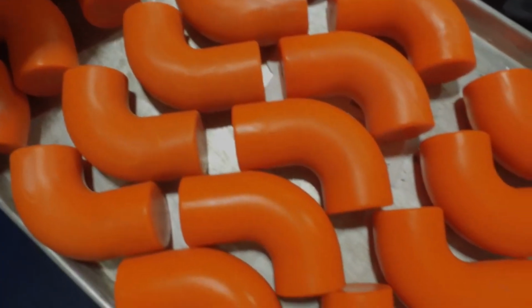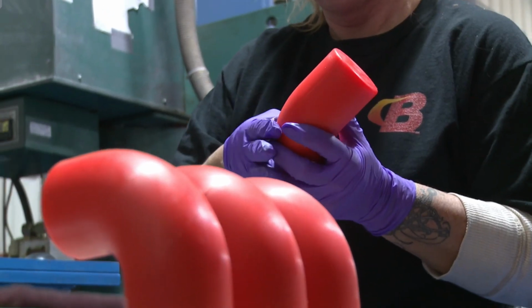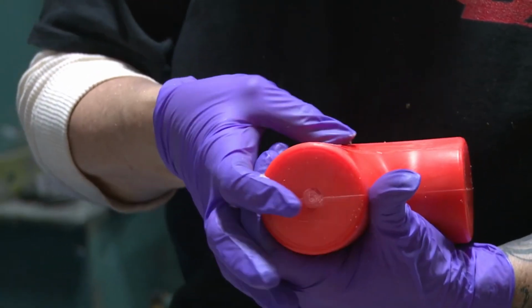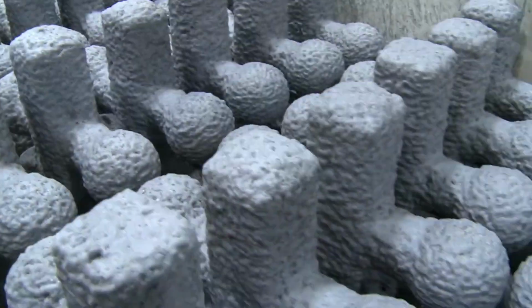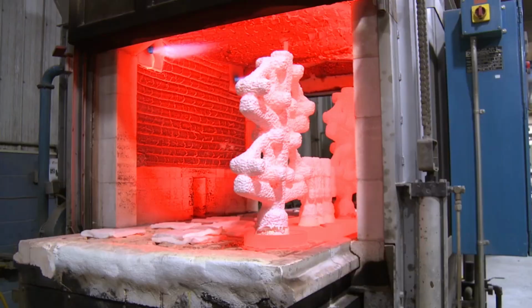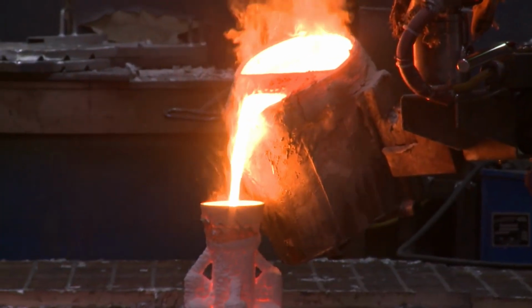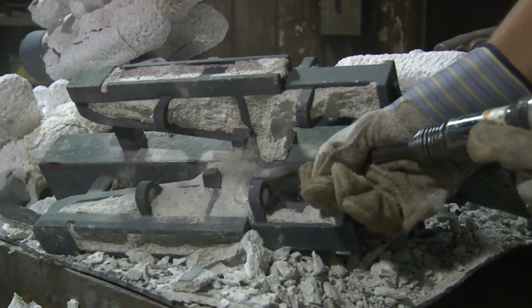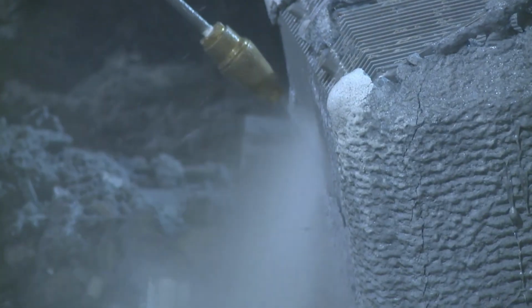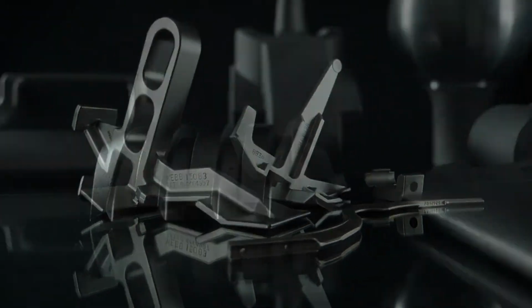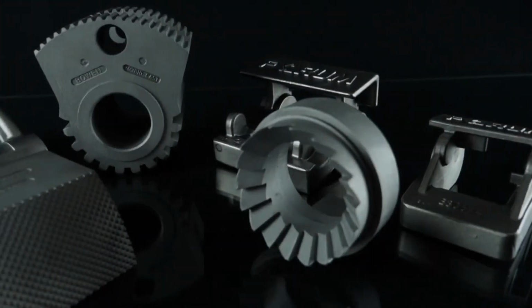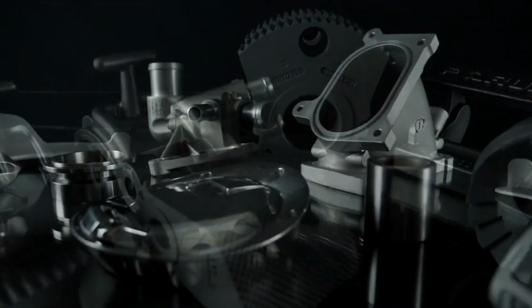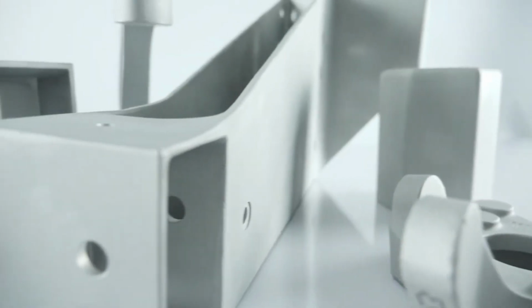In investment casting, the parts to be cast are formed in wax, as a pattern, and coated with ceramic to create the mold. After the ceramic mold is hardened, the wax is melted, and the liquid metal is poured inside the mold cavity, where it is cooled down and converted into a solid metal with the desired shape. Investment casting is capable of producing parts with a complexity that other metal forming processes cannot produce. There is hardly any shape that cannot be fabricated in investment casting.